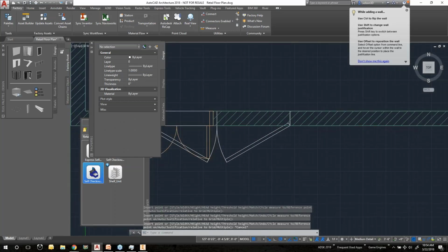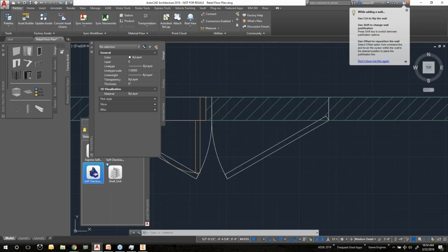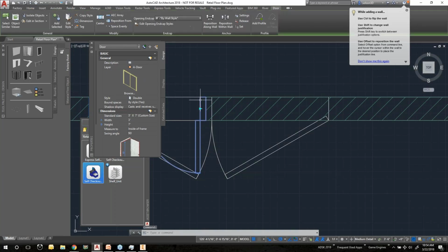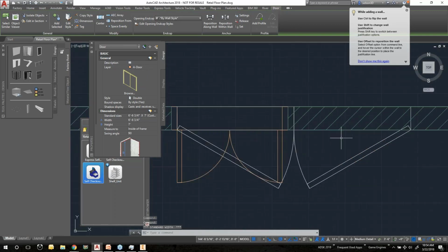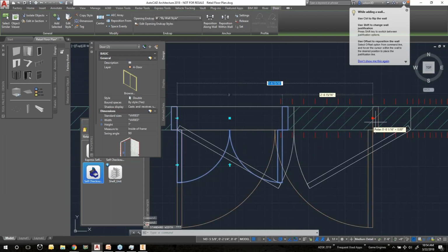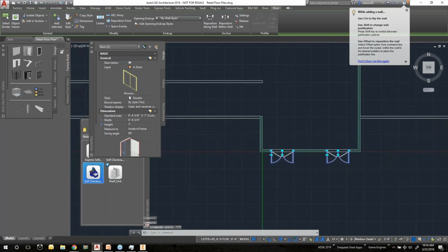Well, AutoCAD Architecture has different sizes of doors. So if I can click on, let me get out of the command I'm in and click on that door, it will let me resize it. And you'll see that I get little tick marks here. Once I click this arrowhead, I get little tick marks showing me standard sizes. So I'll pick a standard size for that one, come over to this one, do standard size for this one. All right, so now I've got my walls in there.